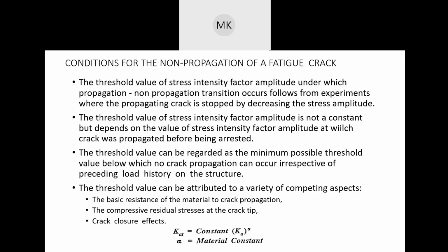but you can easily understand that the reason why the rate at which the propagation happens decreases or stops, is when you reduce the stress amplitude applied. So once you have a major stress amplitude, and then you have reduced the stress amplitude in the material, then all the crack propagation that you have in the material is arrested and doesn't grow anymore.